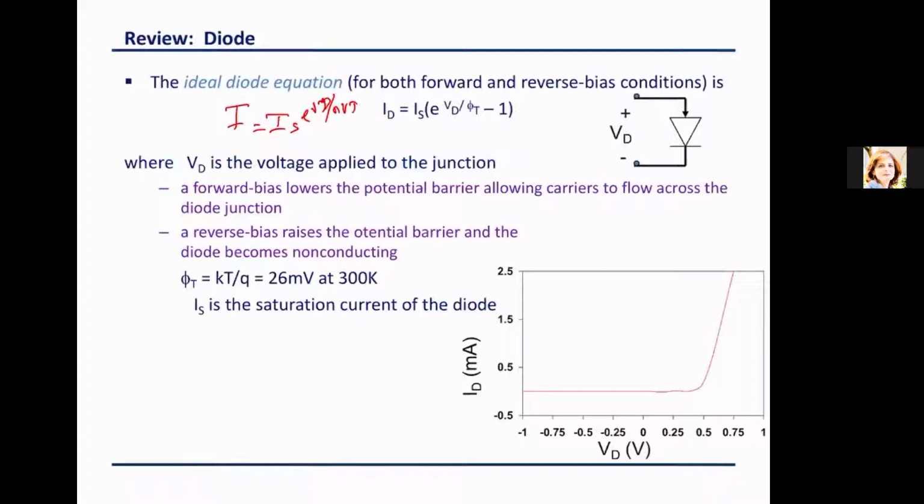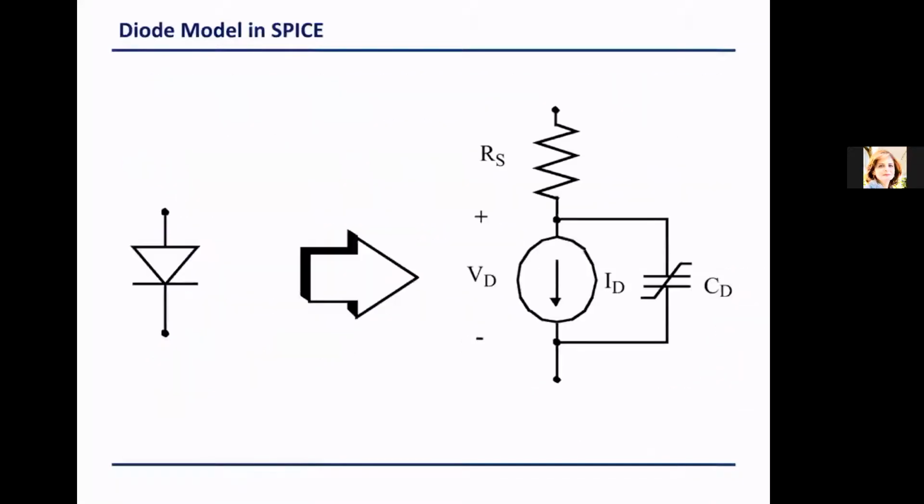So these equations are really a model that I obtained for the device behavior, just like saying Y is equal to e to the AX over C. So X is my input and Y is my output, and we defined that it has two regions, the reverse bias and the forward bias. In a similar fashion, we build the device model. However, just for your knowledge, in the SPICE simulator, the previous equation was a hand calculation, meaning we said Y equals e to the AX.